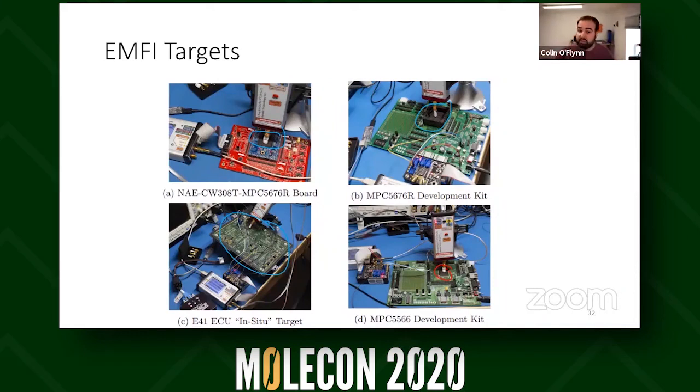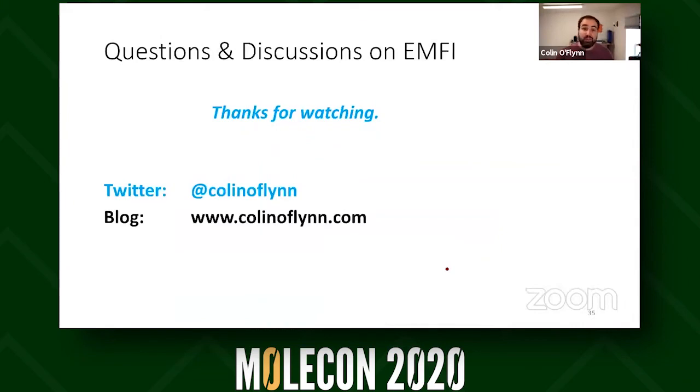Especially in multi-core devices with a secure boot where a separate core brings up the device, you may want to concentrate your glitch effect on one portion of the chip. Even without multi-core, you typically will need to concentrate with EMFI. So there might be things you can do with EMFI that voltage glitching makes more difficult, but we've seen voltage glitching work on quite a few different interesting devices lately, so I wouldn't discount it.